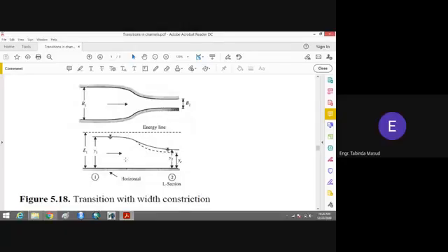So this figure will be opposite. Here you will draw the lower depth of the flow for the supercritical state, then you will draw a hydraulic jump, and after the hydraulic jump you will show that the depth of the flow has increased in the contracted section of the channel. Just make a figure opposite to that figure. There the depth of the flow is higher, which decreases in the contracted section, but in a steep slope you will show that there is a low depth of the flow, and after the hydraulic jump it gets higher in the contracted section of the channel.